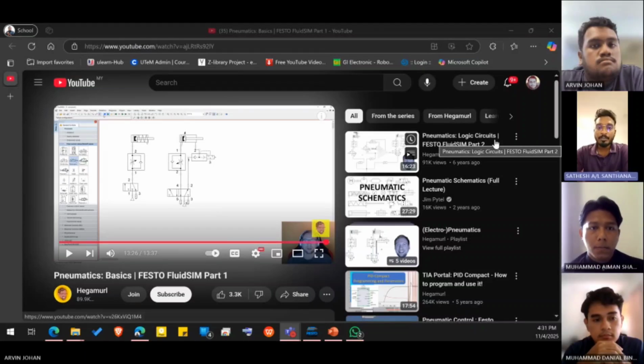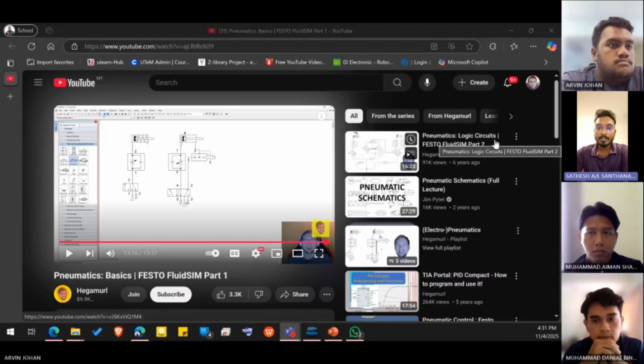Without the spring, we use 5/2-way valves with 5 ports and 2 positions. Port A sends air to extend the piston, while port B retracts it by reversing the flow. In our FluidSIM test, we use a lever switch to alternate between positions. This type of actuator is usually used in robot arms, machine tools, or automated doors, where two-way motion and control are required.